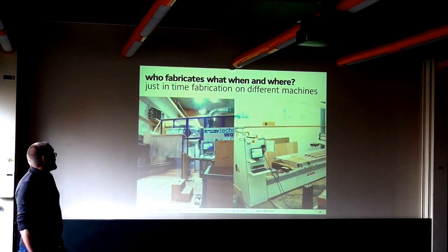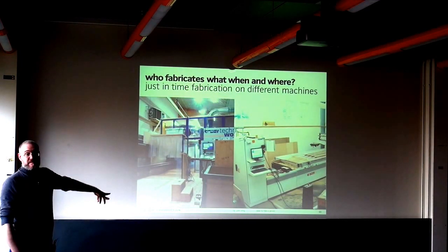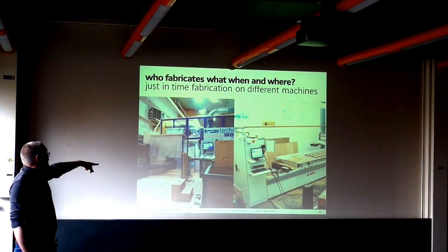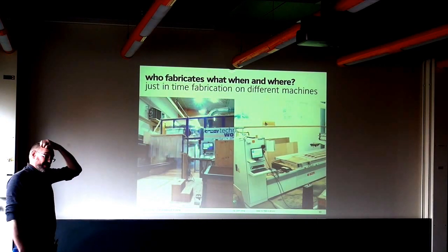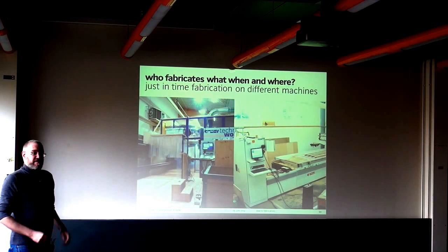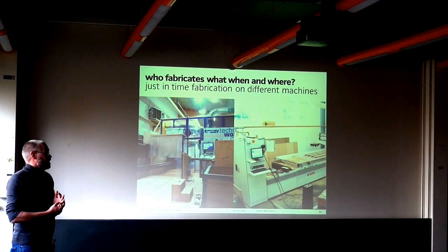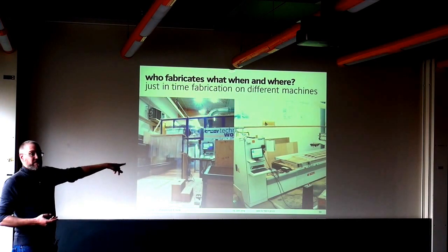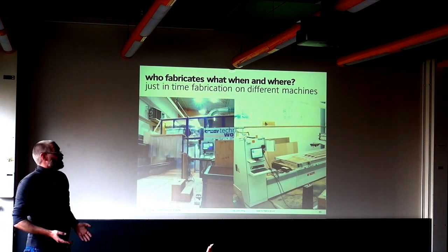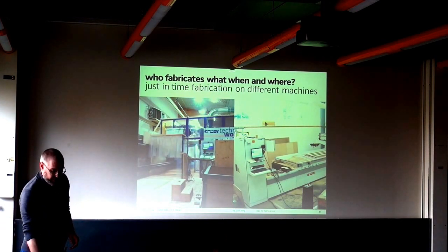Usually on larger projects, you don't work on one machine, but on many. For the Norwegian project, the left one was doing the large curvy timber pieces, a 5-axis Lignamatic machine in Gosau at Blumer Lehmann. On the right-hand side, a 5-axis milling machine that did the 12,500 cladding boards. And there were 1,200 kilometers in between those, because the right one is standing in Norway, but we had to provide fabrication data to both of them from the same model in a way.